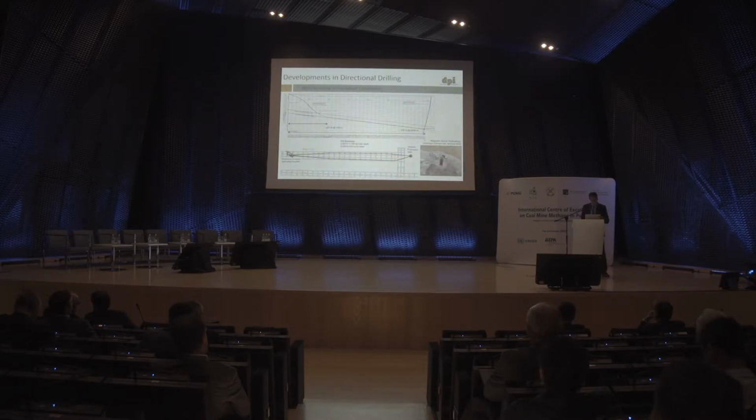The third development that I want to talk about is the use of magnetic ranging to intercept boreholes. So we've intercepted 2 directionally drilled boreholes that were developed from underground. We've intercepted vertical wells that were developed from surface and intercepted them from an underground well and borehole. And then what we're showing here is actually intercepting a lateral with a vertical well. And what this does is it really provides some really new, unique methane drainage solutions, pre-mining drainage solutions.